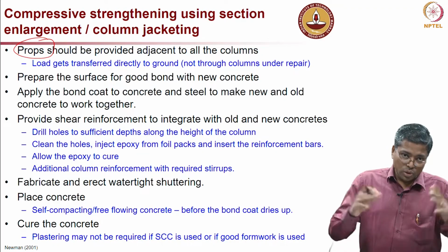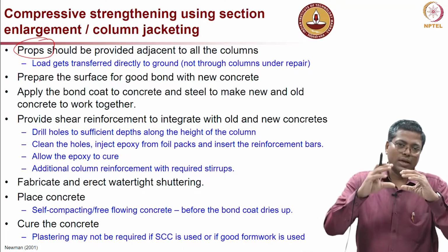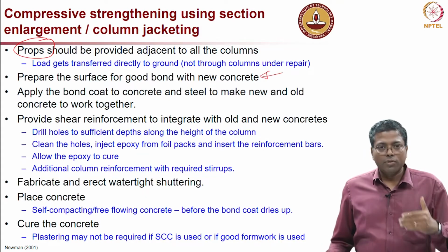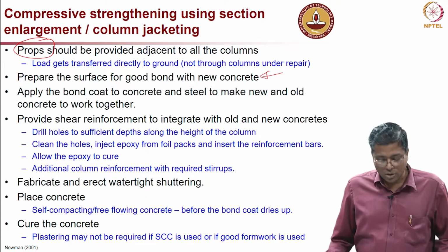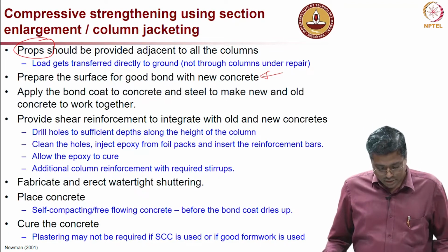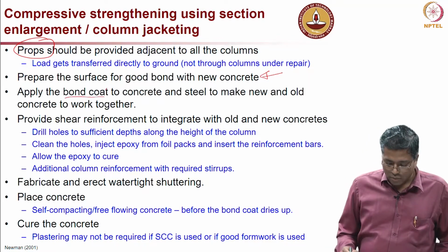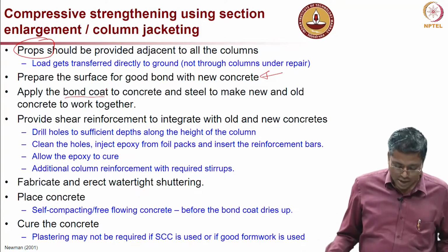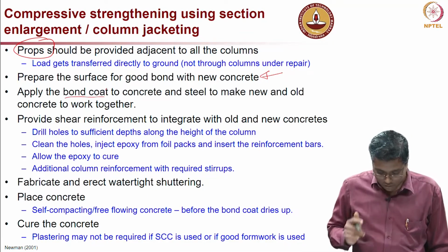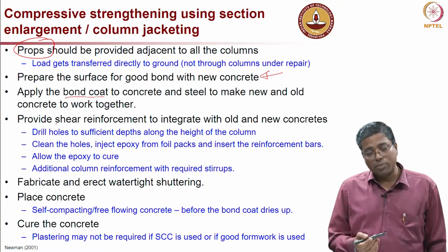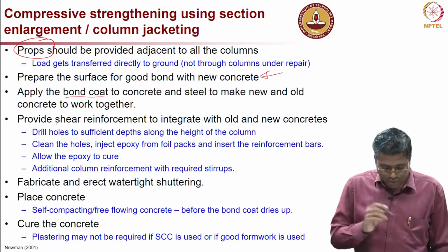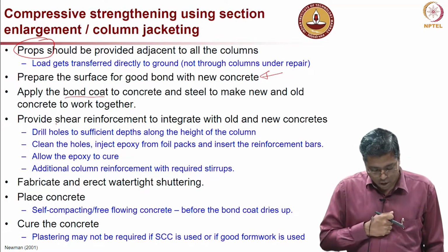So that when the new load is applied, both the existing and the new concrete take the load together. Another important thing is to prepare the surface of the existing concrete very well, so that the new material will bond well with it. Apply a bond coat, or provide shear anchors. There are many ways by which we can enhance the bond between the two.